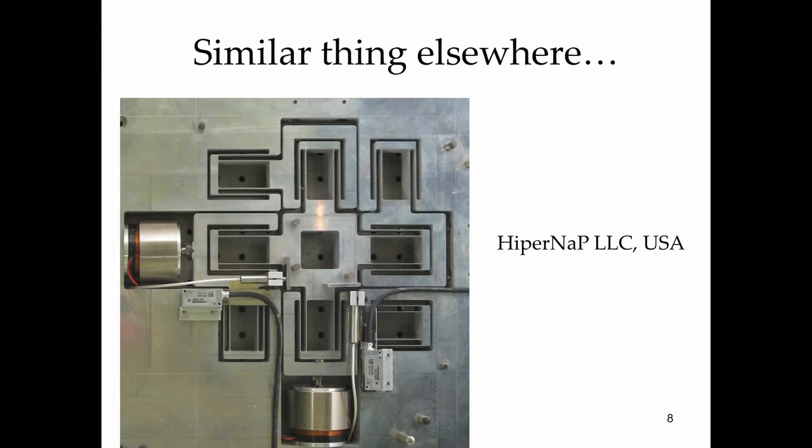If you want to put in a single layer, the previous one had 8 blocks. Let us go back and look at it. As already counted, 1, 2, 3 in the top row, and then 2 in the middle, and then 3 in the bottom row. These things are arranged. If you look at this one, this is upright, this is upright, this is upright, this is upright. So, 1, 2, 3, 4 are upright, and these are 90 degrees turned, 1, 2, 3, 4, half of them. When you arrange them in this particular configuration, you decouple the x, y degrees of freedom, even though it is all made of one piece.